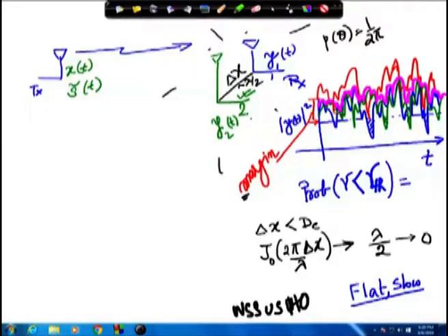Then what we see is that even though these individual links, the blue link and this green link, go below this threshold, whereas this pink color, which is riding the crest of them, which is taking the best of the green and the blue, is hardly going below this threshold. There might be occasions, but in this particular diagram we do not have it. So, what we see is that by virtue of getting independent signals in these two branches, the probability that the received signal strength goes below the threshold becomes very, very low. We can make it very, very low.